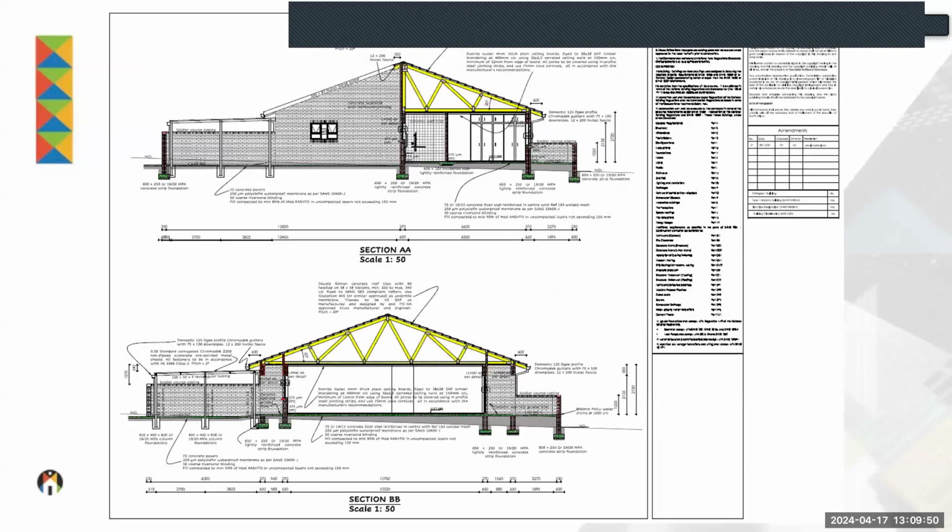Sections, make sure that your section is of such a scale that you can show detail. Remember, you have to communicate to the contractor and to the local authority. I've seen a lot of 1:100 sections with not even the basic information in there, where details are wrong, etc. So a section is basically a detail. If you cut that building into two parts, how does it look? What do you see? How is everything there? And also then the detailing there.